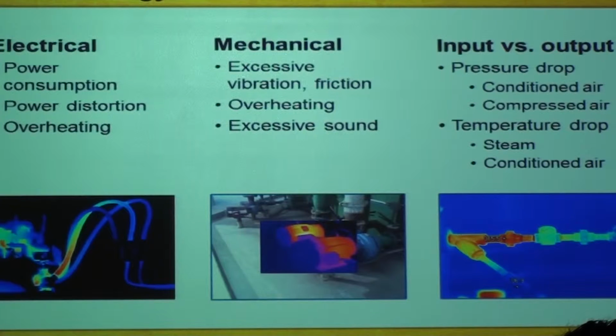Overheating: transformation to thermal energy. That overheating is a waste of energy, and that's what you want to measure in the electrical world. Okay? An example here, thermal imaging is a very good tool that's used to measure and quantify electrical systems.